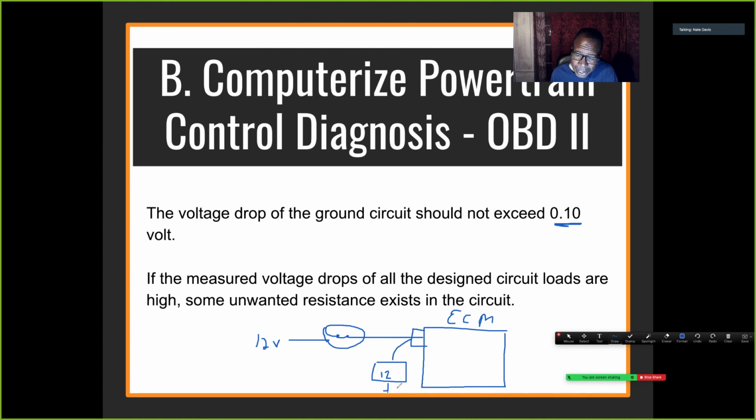If this circuit is energized, and I'm reading 12 volts on this line that goes into the ECM, the transistor is not working for some reason. If it goes down to 0.1 and it's energized and the circuit doesn't work, the load device is not working. You get it?